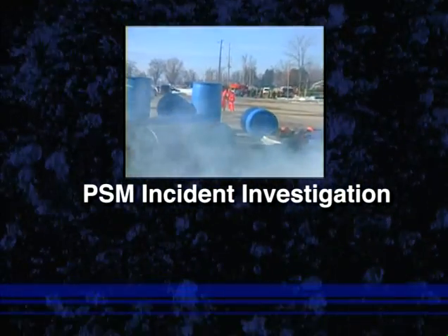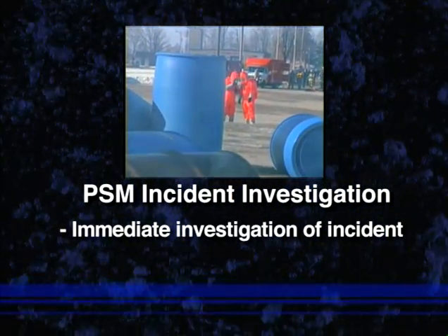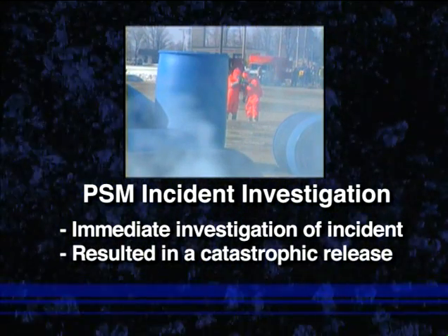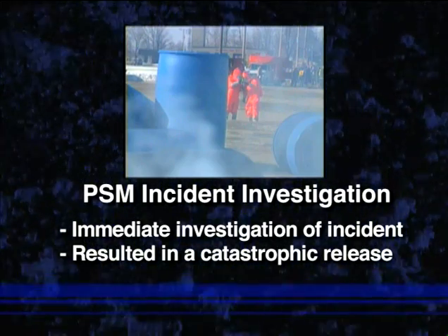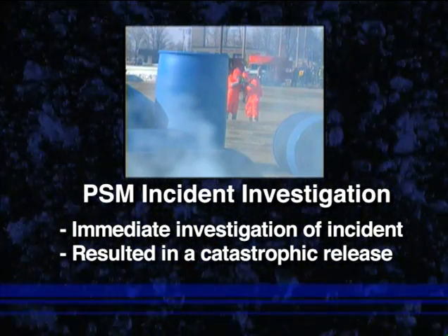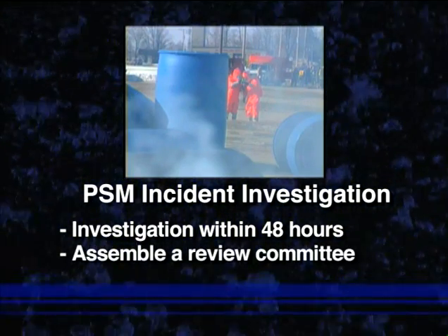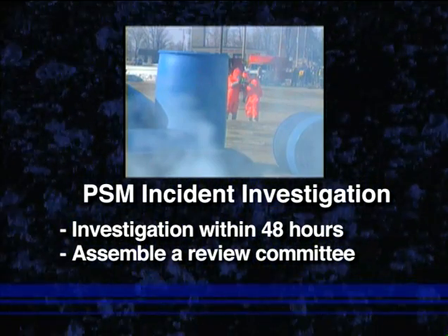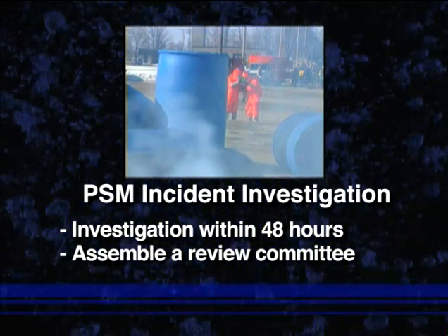Accordingly, PSM requires the immediate investigation of each incident that resulted in or could reasonably have resulted in a catastrophic release of a highly hazardous chemical in the workplace. An incident investigation should be initiated as promptly as possible, but no later than 48 hours following the incident. A more thorough intensive review should take place later when an appropriate review committee is assembled and available.